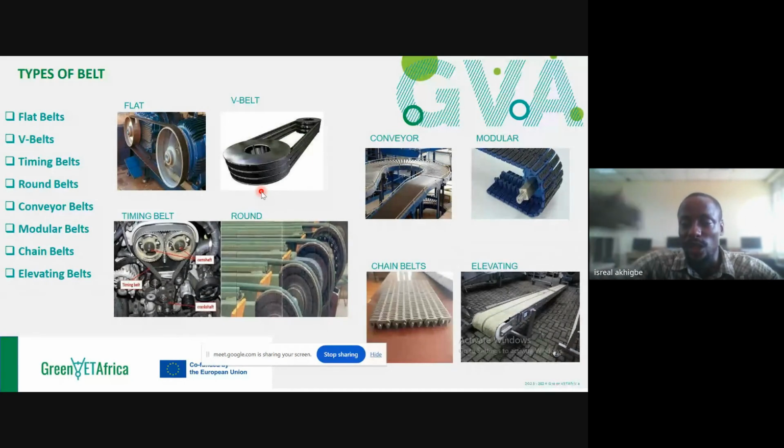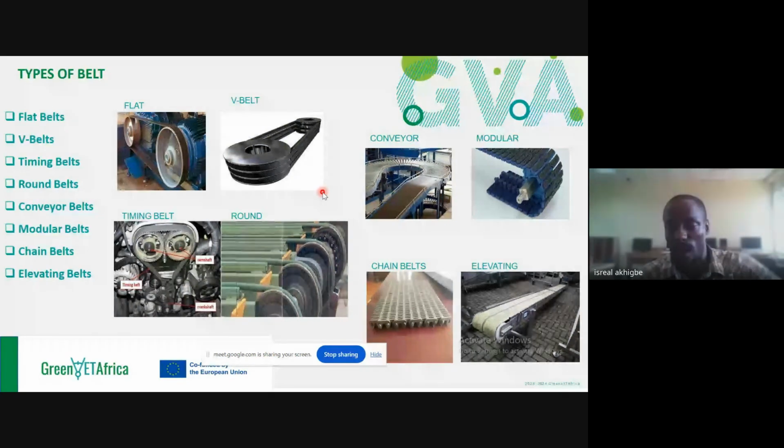That way the torque, the turning force that is required to transmit from driver A to driven B, is spread across multiple contact surface areas of the V belt. That's why this multiple pulley uses V belts. You can have a single pulley and a single V belt for light and easy transmitting of waste material, or transmitting motion to a portion that does a very light amount of work. But if you want to transmit some serious torque, you can have cone pulleys, rather step pulleys like this, with as many as 5 or 6 grooves, to be able to transmit enough torque.